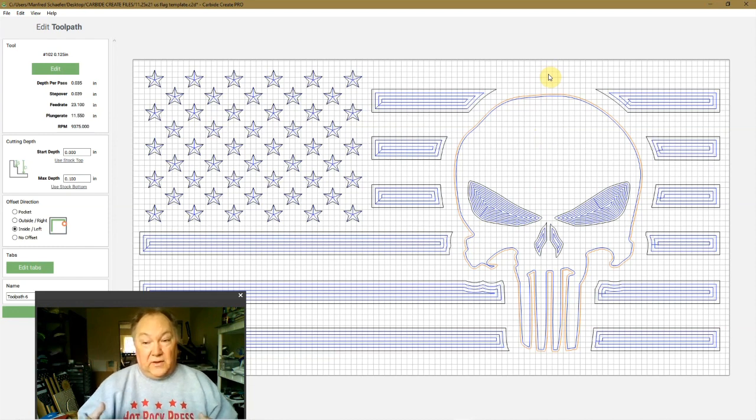If there's a bit change, which there's not here, but when there's a bit change with Carbide Motion and you do your G code all in one click, later I'll show you where to do the G code, the clearance isn't enough to change the bit, so I never do it that way. What I do is I set a G code for every bit separately, to avoid that. So anyway, you click the outside, then you go